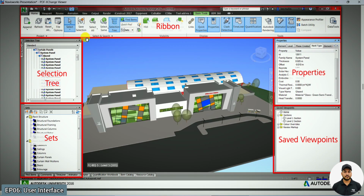Okay, next, this is our interface, the main working interface. You can see our model will be visible. Here we have a navigation toolbar, with the help of which you can rotate the building, pan, and zoom in and out. And this is our 3D view cube, with the help of which you can see the directions like top, back, bottom, left side, and also the north, south, east and west elevations of the buildings.